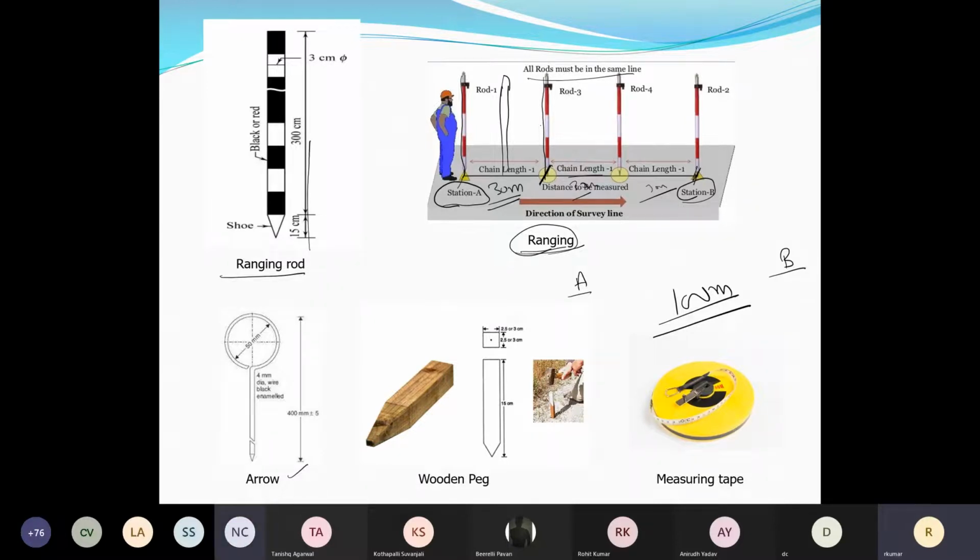Okay, so every 30 meters I will put an arrow. So in the field, I can count the arrows and measure how much chain I have used.